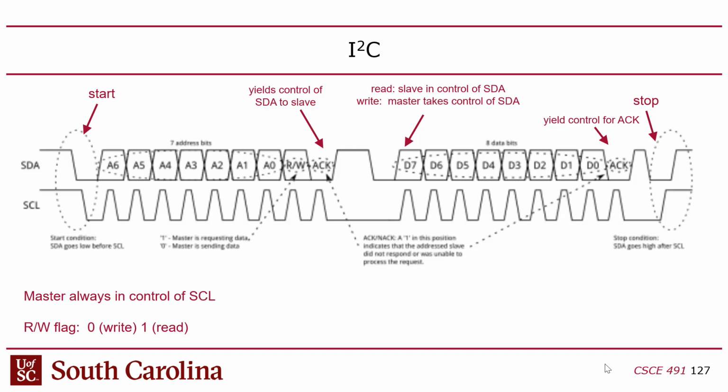But if it's being done as a way to wake everyone up and to take mastership of the bus, then it's okay, right? So basically, the start sequence is I pull data down, right? That gets everyone's attention because they're like, oh, that's not allowed, right? That gives me the bus, and then I pull clock low, right? Make sense? Okay, so then I have mastership.